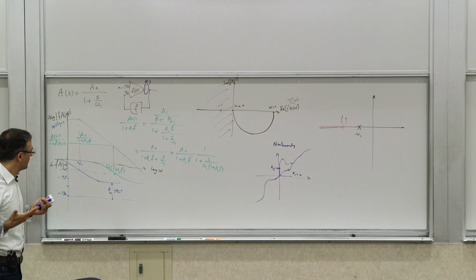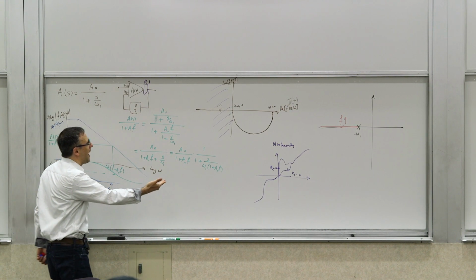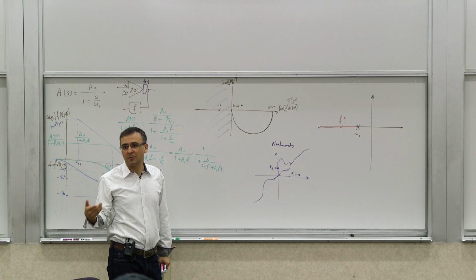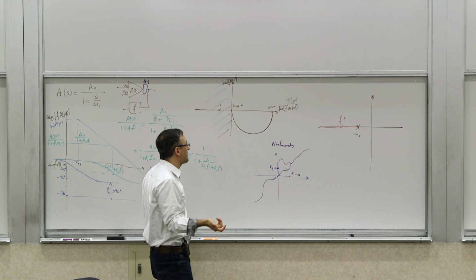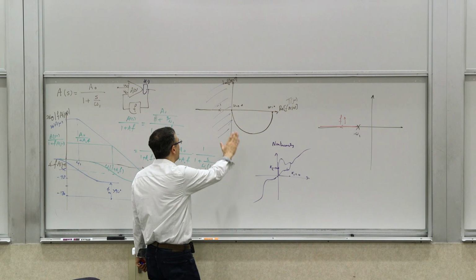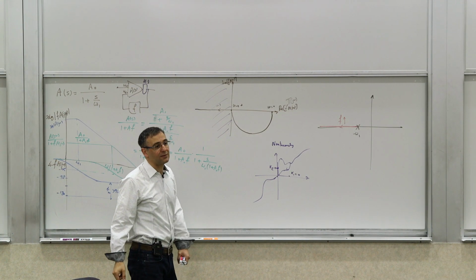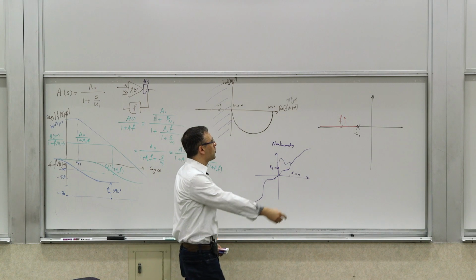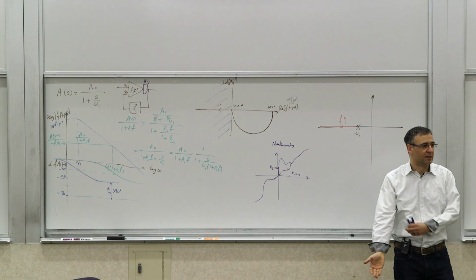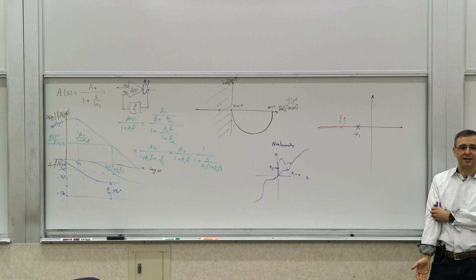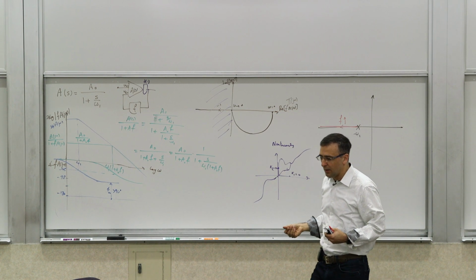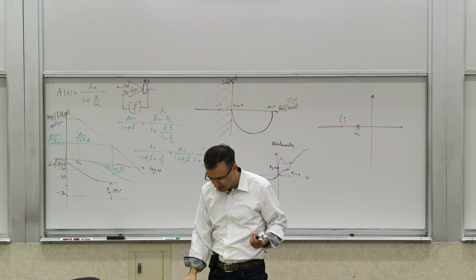All of these pictures. You see you have a lot of phase margin here. From a Nyquist perspective, you're not getting anywhere near point -1, let alone encircle it. From a BIBO stability perspective, from an absolute stability perspective, for any kind of nonlinearity in the first and third quadrant, as long as you avoid the left half side, you're stable. Your pole, as you increase the feedback, gets pushed out. So it's a very stable system. You don't need to worry about anything. So that's like a first order system. So no major surprises here, I guess.